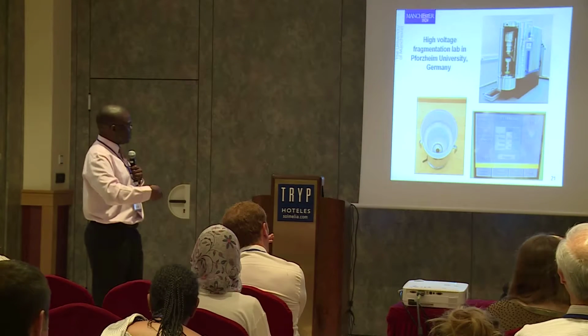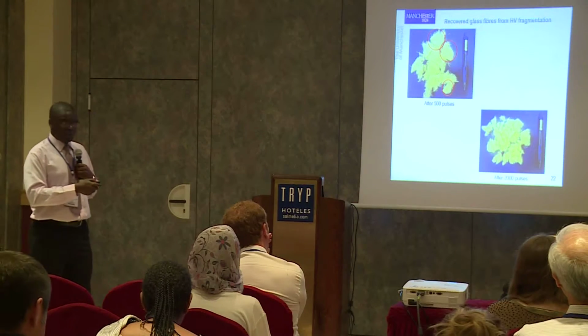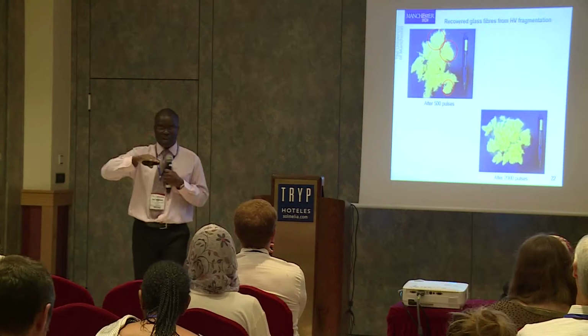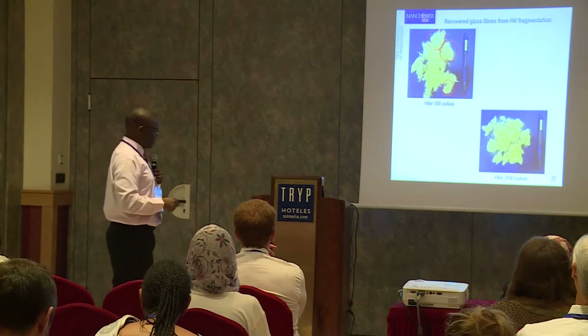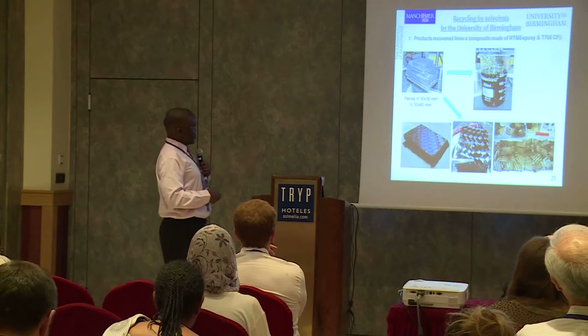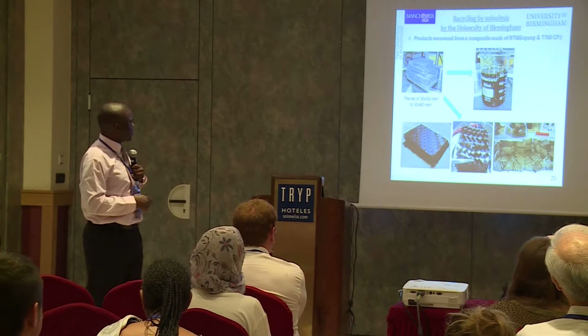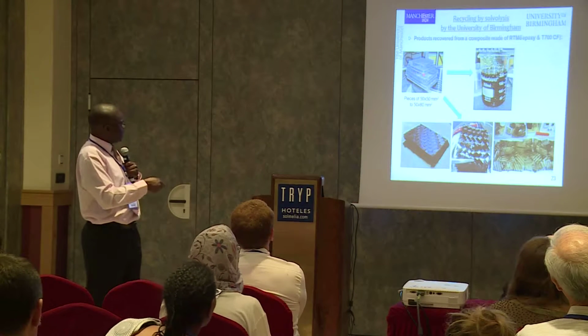And this is the equipment inside, and that's the result. So I started with my composite fiber. Through the shock wave, I'm able to fragment the composite, and then I wash out the resin, and that is the remaining material. So the other process I could use is chemical processing. In this case, I start with these composite panels here.